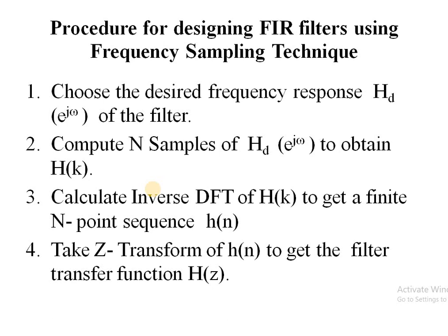With this little introduction, now we shall move forward to the procedure or the steps in designing FIR filters using this frequency sampling technique. The first step is to choose the ideal or desired frequency response from the given specifications in the design problem, and clearly note down the H_D of e power j omega.